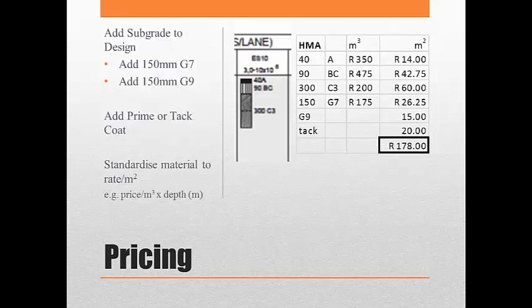Within the course design context, the cheapest catalogue is chosen based on the present material cost only. For the purpose of our design calculations, no other criteria will be considered. However, in a project environment, we call it value added and ask the student to evaluate additional criteria. Please note that the present worth of cost is only established in the present year where the maintenance is 0. However, should the cost be considered for the analysis period, the maintenance and rehabilitation would have to be considered, as well as escalation thereon.